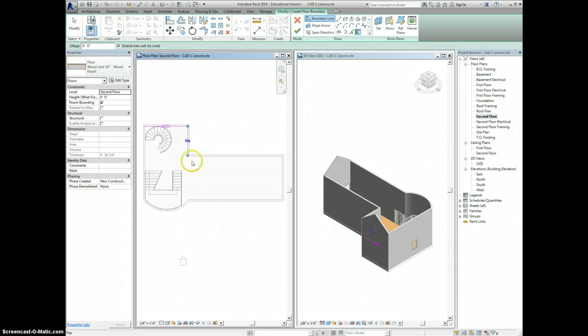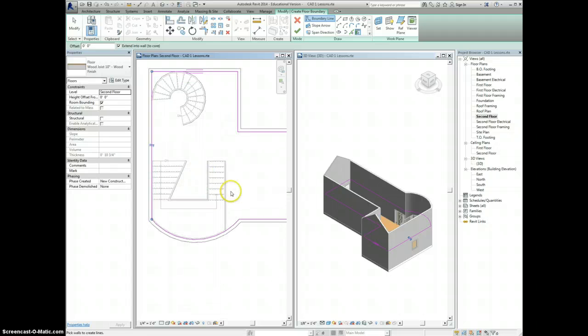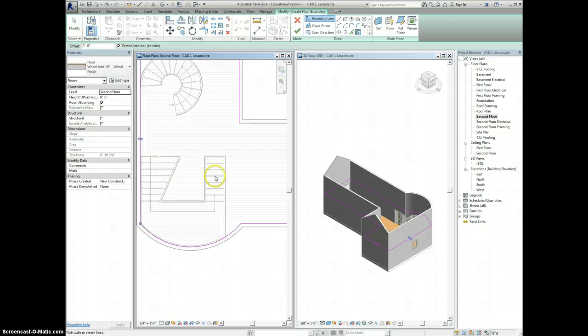And this time we're going to pick the inside walls instead of the outside walls, so that they kind of stay inside the house. And if you pick the other way around, you'll know what I mean. Now the tricky part is with our stairs here and here. We know this is the top of the stairs, and if I were to finish this and then click on the stair, you would see that each of these risers is 11 inches tall. We want at least 7 feet clearance between the person's head and the ceiling at any point in time throughout the stairs. That would mean we need to account for at least 8 steps, or about 8 steps, 7.5.